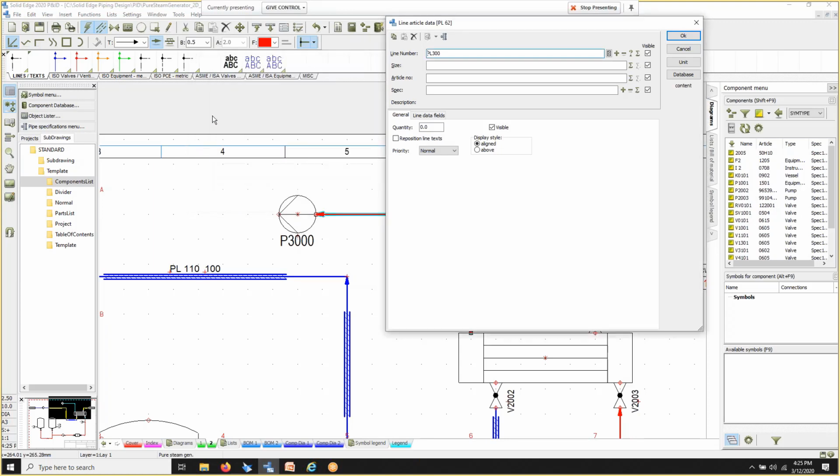Okay, so we can come in here. I'm going to go with this PL300, even though I'm not really using acid. But we'll just say, hey, this is a PL300. Has this been used before? No, so it doesn't really matter. Now, for the rest of the information here, do I want to type it in? I could. However, manually entering data is a little bit error prone. So we can actually come up here and pull the information from our pipe specifications.